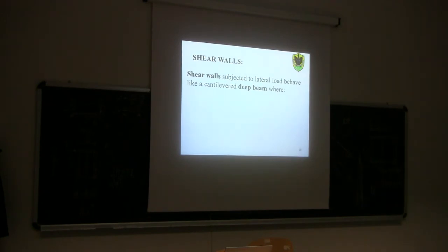So one stud is compressed. Then underneath the stud there is one plate, and then underneath the plate there is a foundation. Through the plate, which kind of verification will we have to do? Again, we have to do a verification of compression perpendicular to the grain here. And then we have direct contact to the foundation, nothing more.